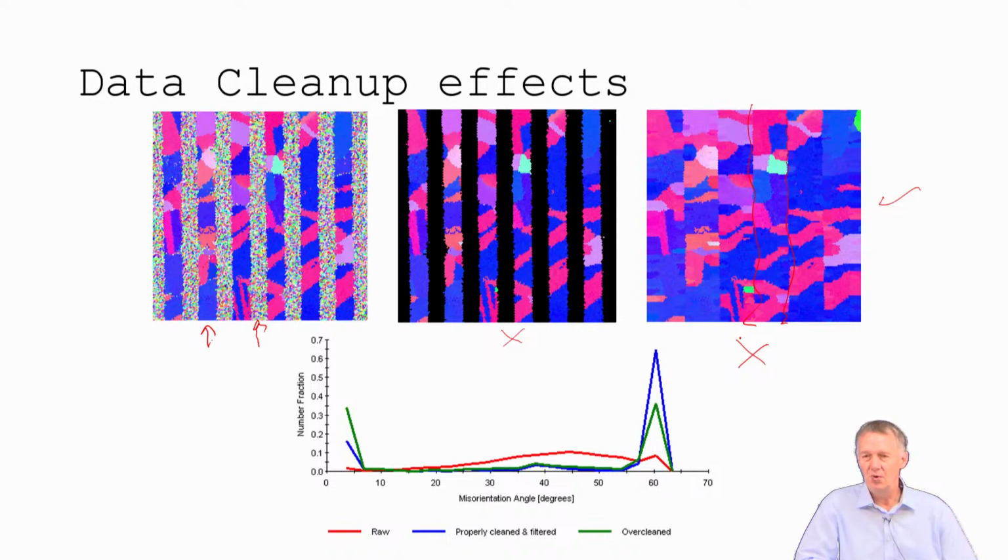One of the beautiful things about that, which is really not beautiful, is you can have an entire data set from an amorphous material like this dielectric, where it's all just speckled everywhere. And then you can use cleanup strategies to get a nice perfectly equiaxed data set, right? You can have nice grains defined, just completely artificial data. So always be careful with that.